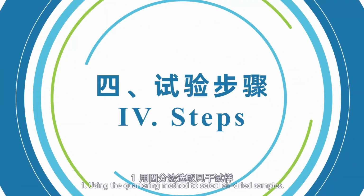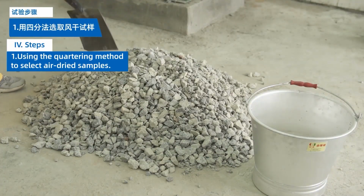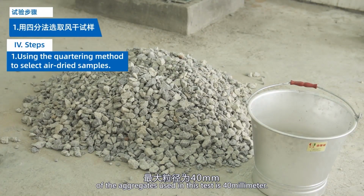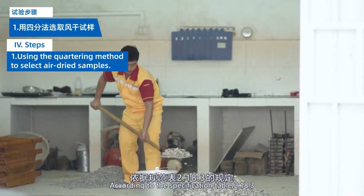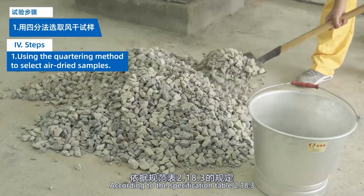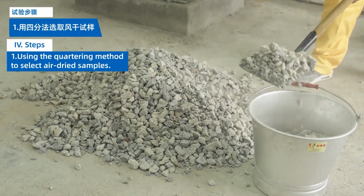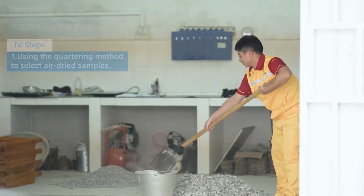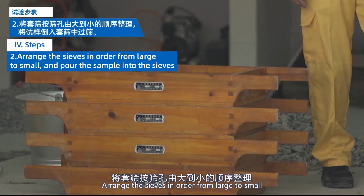4. Steps. 1. Using the quartering method to select air-dried samples. The maximum particle size of the aggregates used in this test is 40 mm. According to the specification, Table 2.18.3, the sample should be at least 20 kilograms. Arrange the sieves in order from large to small, and pour the sample into the sieves.